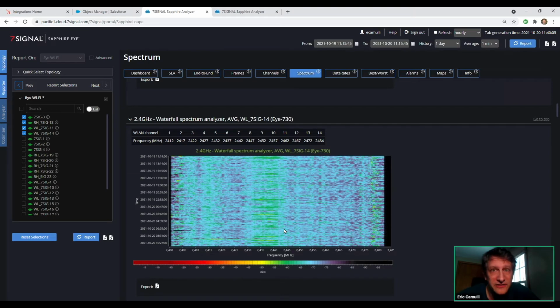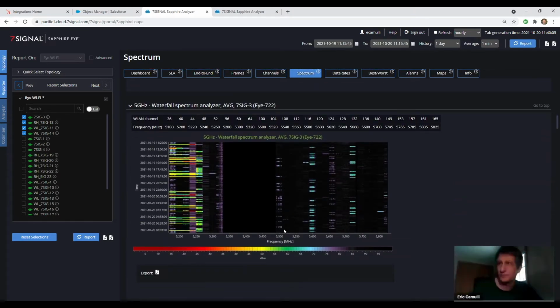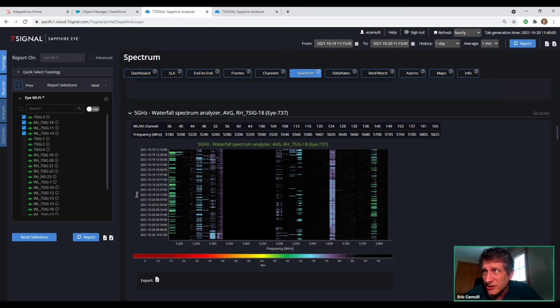You ready, guys? I'm about to get to 5 gigahertz. This is going to freak you out. So here we go. I would not consider this any kind of jamming or weirdness. This kind of looks like 80 megahertz wide channels in effect, quite frankly. Not a big deal. And over here, you can see the 20 megahertz wide channels. This looks really normal. Again, from the beginning of the day to the end of the day, we're waterfalling down, and the Wi-Fi spectral slug is leaving its trail behind, so we can see the energy.